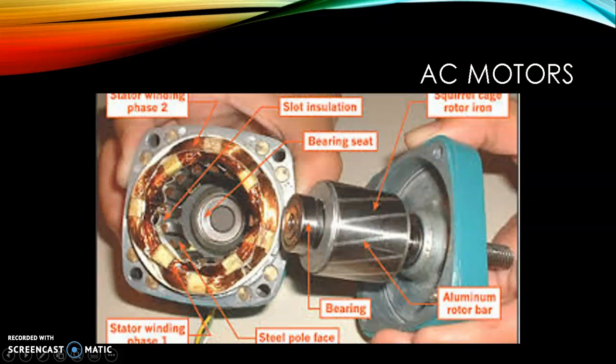To continue, AC motors are run off an alternating current. Unlike in a DC current motor, the AC current motor sends power to the outer coils that make up the stator and energizes them in pairs and in sequence, which allows them to create a rotating magnetic field, which in turn allows the current to begin to flow in the rotor because of Faraday's law combined with Lenz's law, which then in turn tries to make the rotor play catch up with the rotating magnetic field, causing work and power to occur.